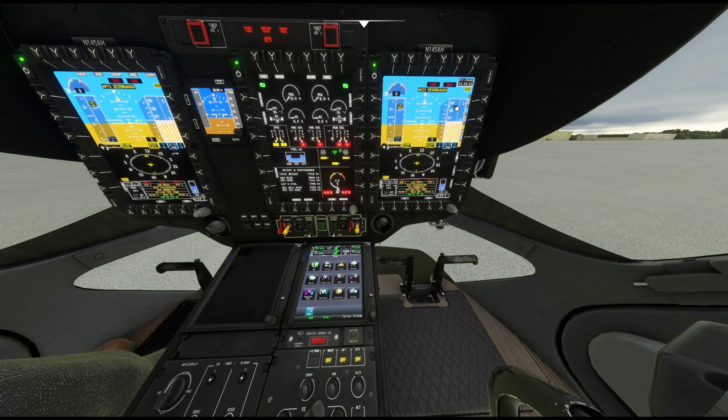Now, we'll take a second here to talk about colors on the autopilot. This brownish color right here is a GPS calculated ground speed. Anything that's got this brown color is a GPS-based calculation. If it's in cyan, that means that you have input that item, but it is not yet engaged. So you have preloaded that value, kind of like if I come over here to indicated airspeed, you see that cyan dot. I have not armed it, but I'm putting something in.